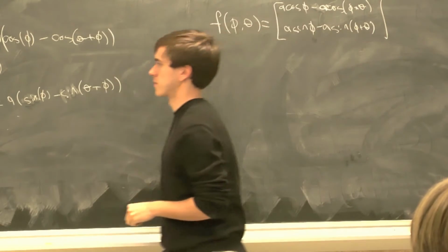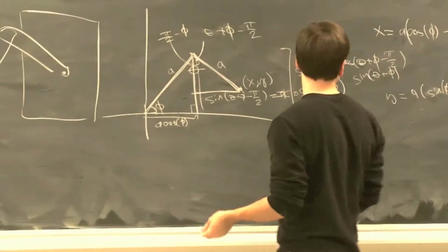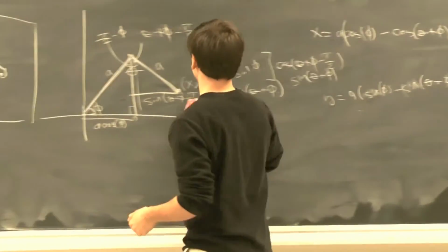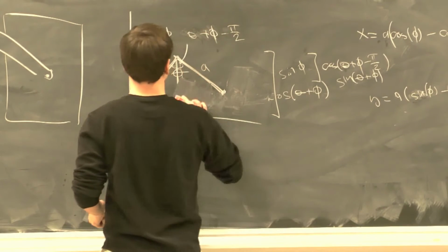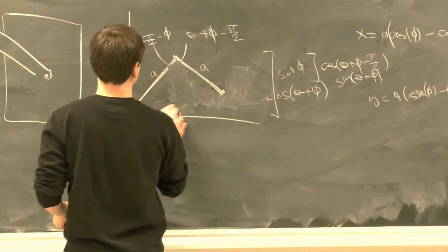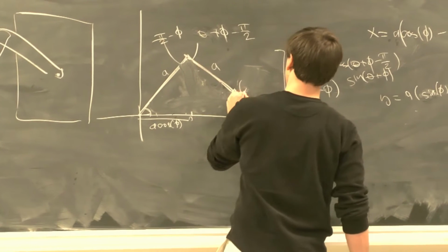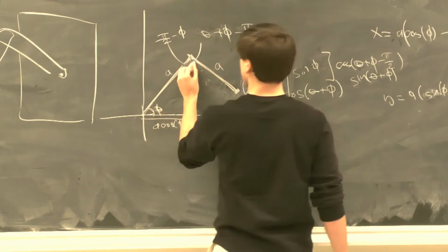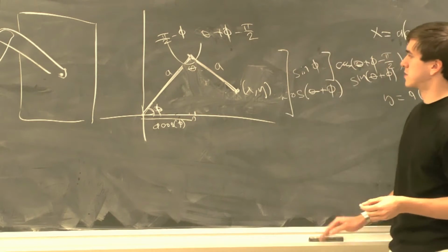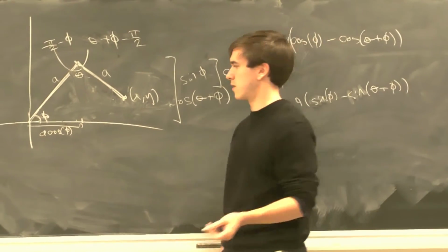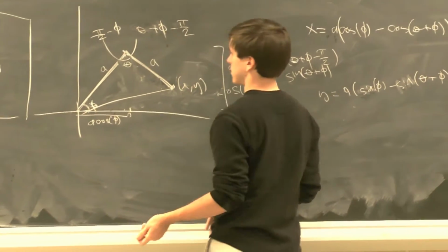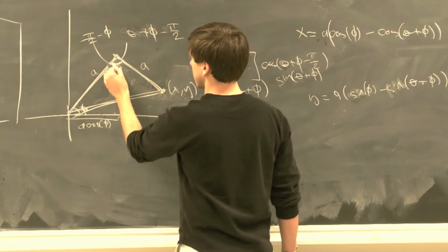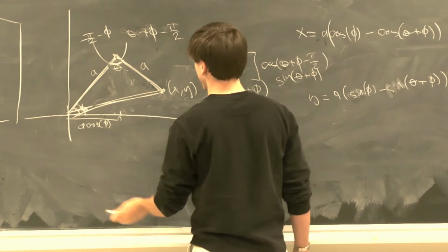And now, to invert this, we can't. This is not necessarily easy to invert by itself, but let's take a look at this. So we have x, y, and we want to determine phi and theta. So this stumped me for a little bit, but what I ended up doing is, this is an isosceles triangle. We can use the law of cosines to determine this angle, and then split it up here. But I'll show you in just a second.